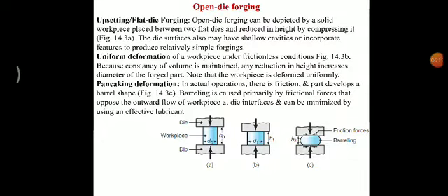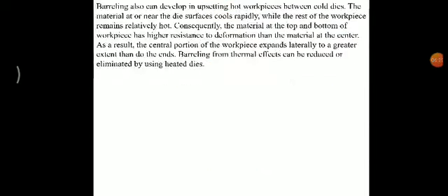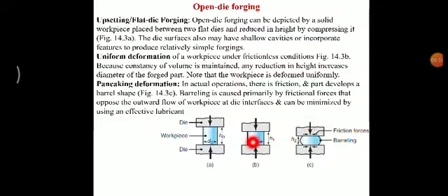Okay, because it is changing its height and diameter, it will be regarded as an instantaneous height and diameter. It will be a very important parameter when we study the behavior of the metal as the pressure comes over the workpiece. At the end you will see a barrel-like structure is formed, meaning the diameter is new, the height is new, and the barrel-like structure is formed.